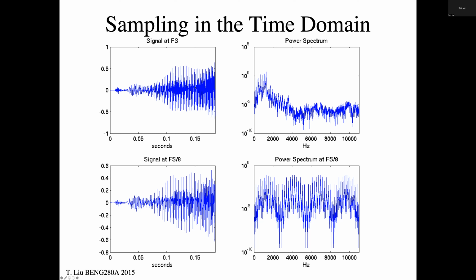So for magnetic resonance imaging, we sample a time domain signal. Look at this example here. We have seconds across here, so this is 150 milliseconds. I have a signal that's oscillating in time with a certain number of frequency components. These points here are a plot of points that were sampled at a particular rate, so a particular delta t in time. And there's my function. In order to analyze this data, we're going to take the Fourier transform of that data,